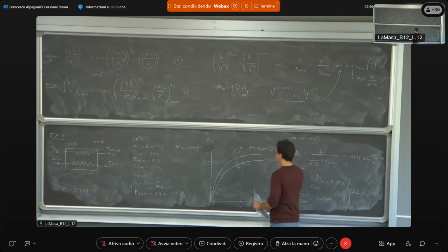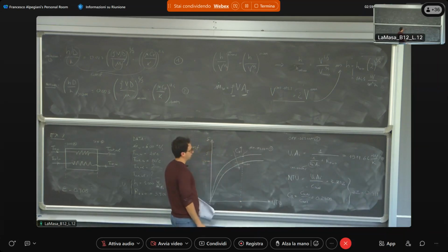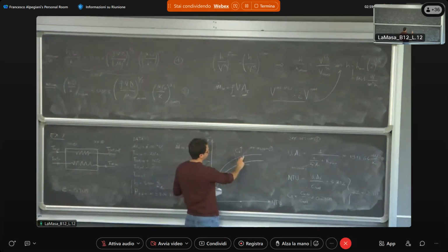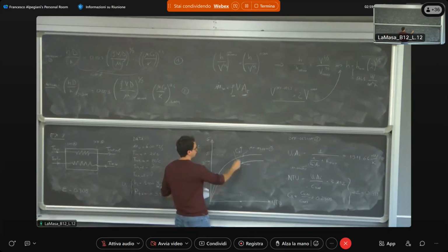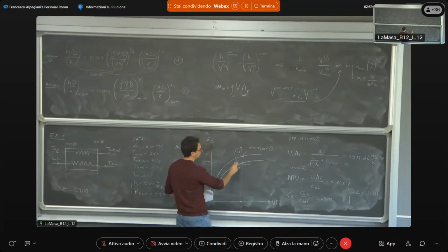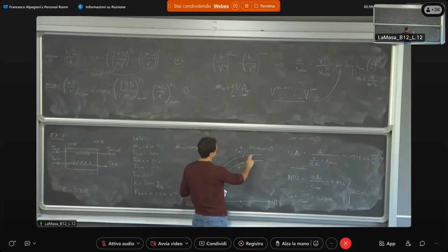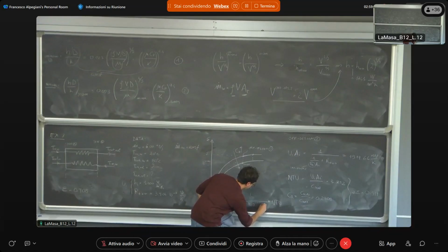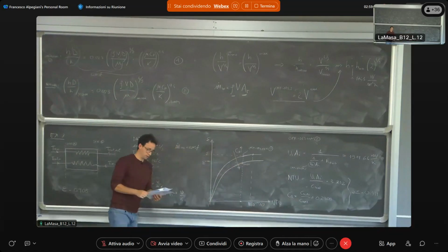So what happens is that in this case, you have the same CR, so you are in this condition. The off-design number 1 and the nominal condition had the same NTU. In this case, you move across the same CR, so across this curve, and you obtain a higher effectiveness because you obtain a higher NTU. Okay, this is the NTU in off-design 2. Okay, it's clear?